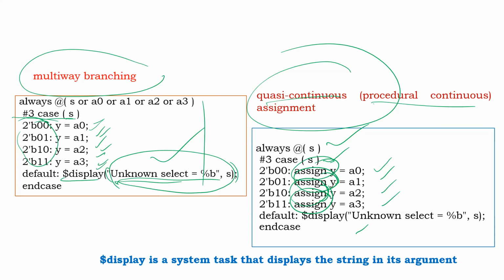Now it is time, because we are going to the edge of all the levels of abstraction, that I am going to introduce the delays. Practically, delays must be there, so the designer needs to intentionally add some delays. There may be different types of delays: rise, fall, and turn-off delays. If a single value is specified, all 3 delays are equal. If different values are specified, you can assign each one. The order is rise, fall, and turn-off. Each delay can again be assigned 3 values: minimum, typical, and maximum.